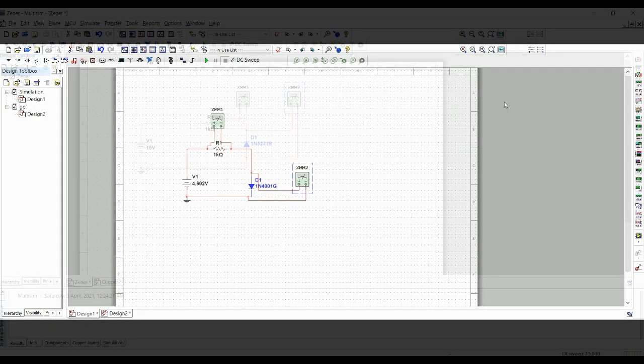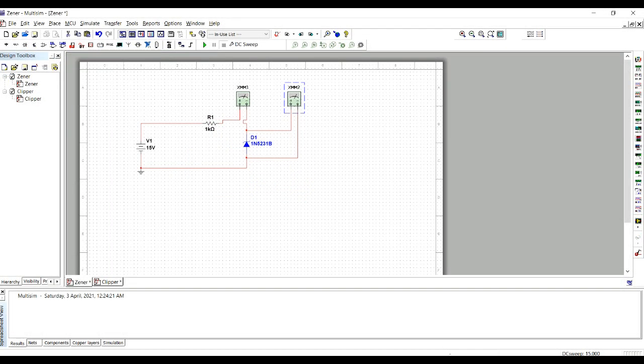Thank you, Checkmaster. Hi, Sim Isa. My name is Fu Junfei. Now I'm going to present about the characteristic of Zener diodes. This is the Zener diode circuit with reverse bias, and the diode we use is the 1N5231B. In the circuit, we have two multimeters. This multimeter is to measure the reverse current in the diode circuit, and this multimeter is to measure the voltage across the diode.